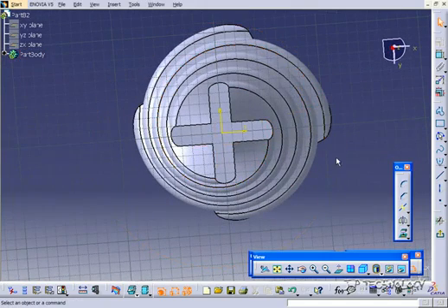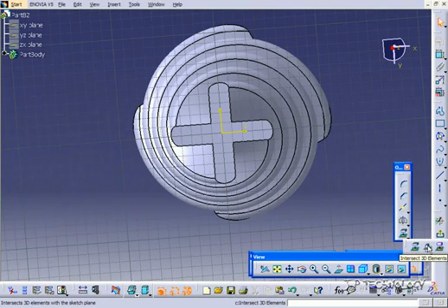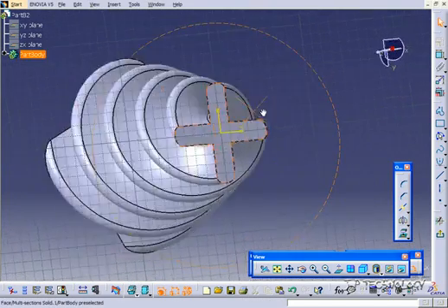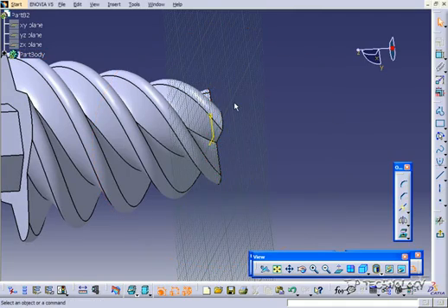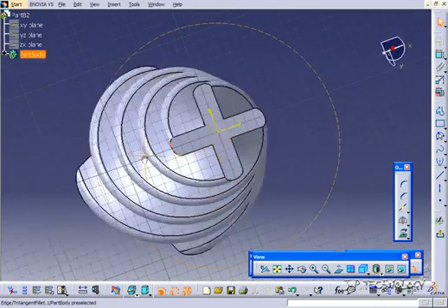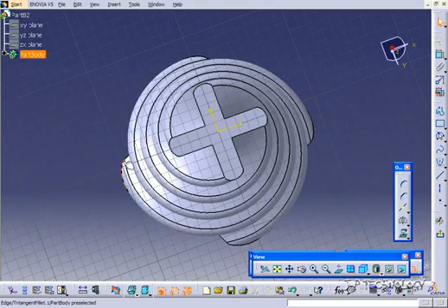To do this, you have a whole set of projection tools. If you look here on the toolbar, you have all these projection tools, and the one I'm going to use the most here is the Project 3D element. We're going to project a bunch of these lines onto this plane that we're working on, and from those we're able to lock into those points or those edges and draw and make components off of it.